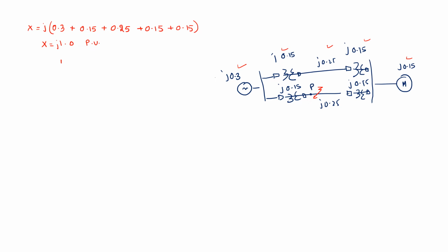So, if I want to calculate the post fault power, the expression will be P is equal to Pm sin delta. So, this Pm, the maximum power which can be transferred, is equal to Eg VT by X. So this Pm can be written as 1.2 into 1 divided by 1, so it is coming out to be Pm equal to 1.2.